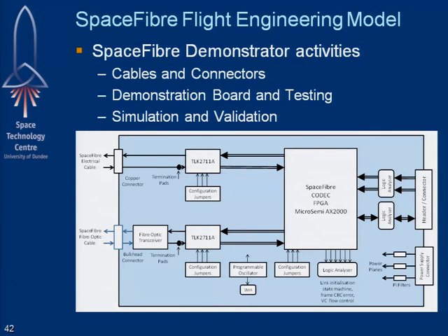We're also working on a SpaceFibre flight engineering model implementation, which is aimed at raising the TRL of SpaceFibre. This will use components that have all flown before, so it will raise its TRL enormously. We'll be using a Microsemi AX2000 device, which will hold the SpaceFibre digital logic, and we're using the TLK2711 as the SerDes. We're working with Astrium in Germany on that board design.